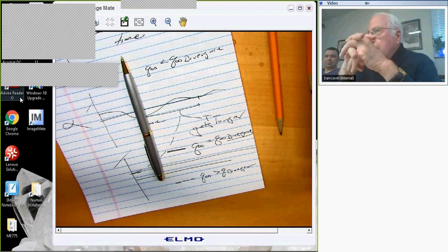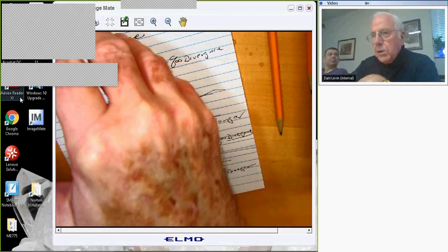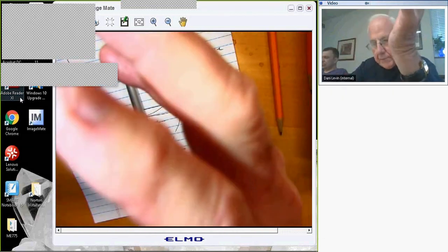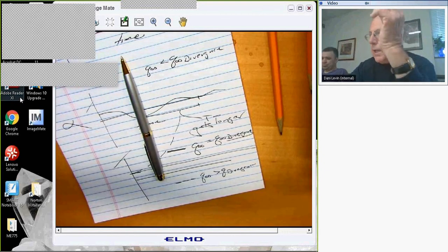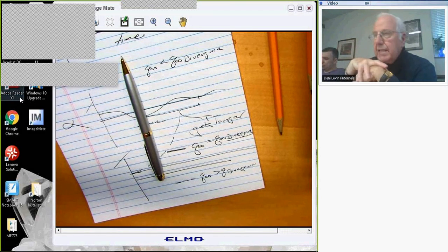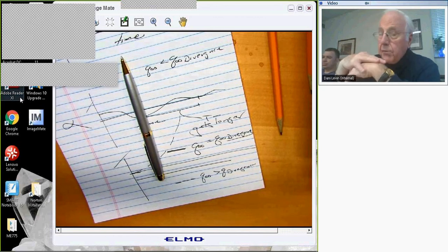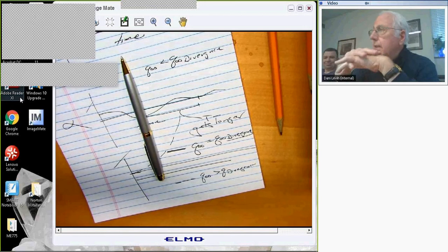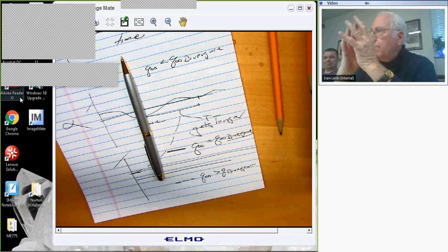As you point out, the divergence is caused by the aerodynamic forces, right? Interacting with the elastic forces. Buckling, if you think of buckling of a beam, of course, is because you apply a compressive load. And it is true that from a mathematical point of view, that compressive load and the aerodynamic forces are providing a similar phenomenon, namely a static instability. In one case, when it's a compressive load, we call it buckling. And in the case of aerodynamic forces, sometimes people actually use the phrase buckling, but it's more traditional in aeroelasticity to use the word divergence. But much of the mathematical modeling of buckling and divergence are virtually the same.